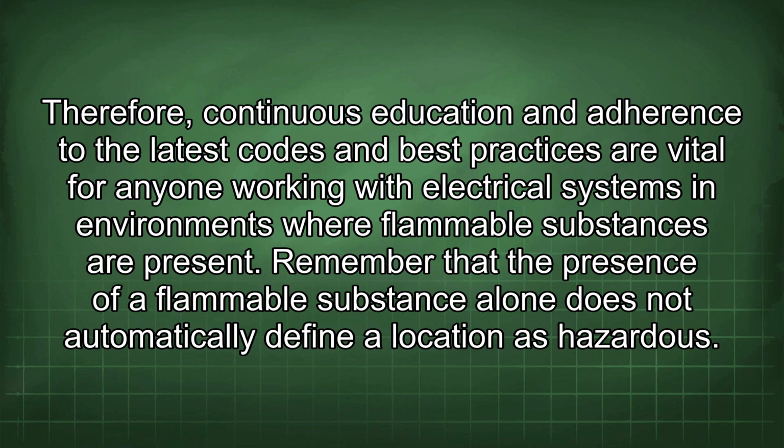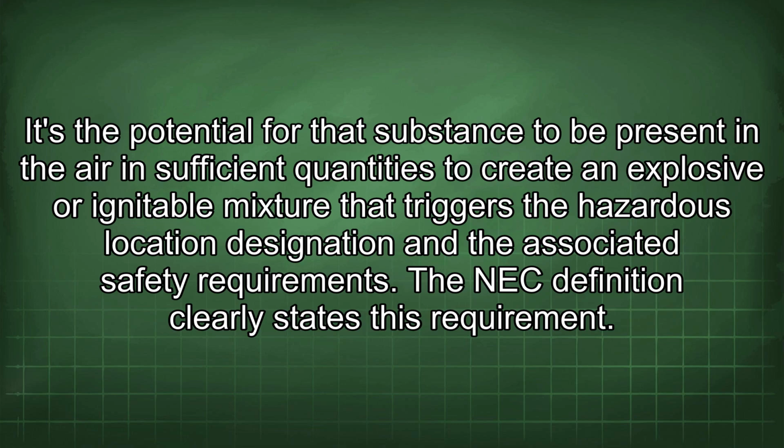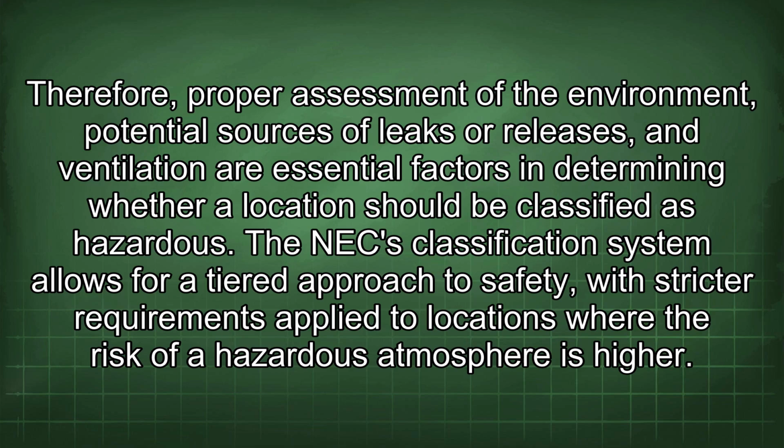Remember that the presence of a flammable substance alone does not automatically define a location as hazardous. It's the potential for that substance to be present in the air in sufficient quantities to create an explosive or ignitable mixture that triggers the hazardous location designation and the associated safety requirements. The NEC definition clearly states this requirement. Therefore, proper assessment of the environment, potential sources of leaks or releases, and ventilation are essential factors in determining whether a location should be classified as hazardous.